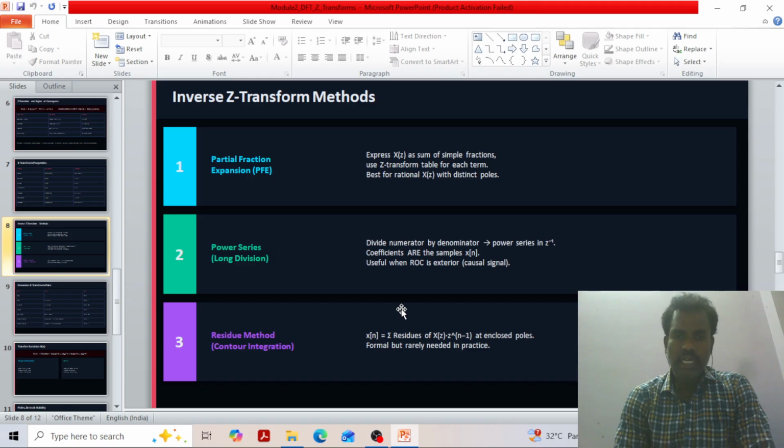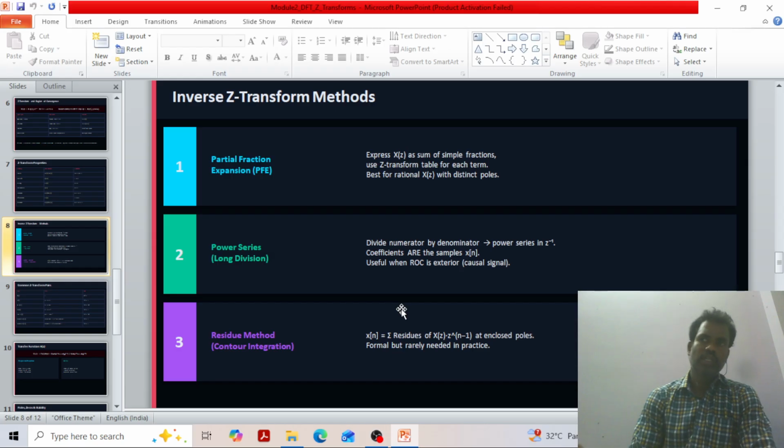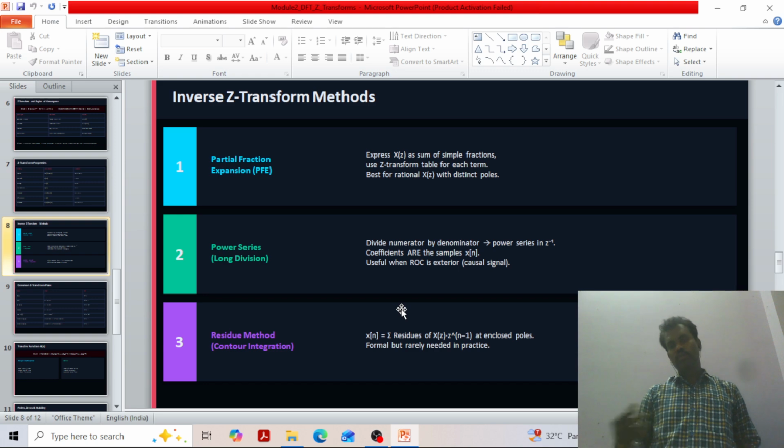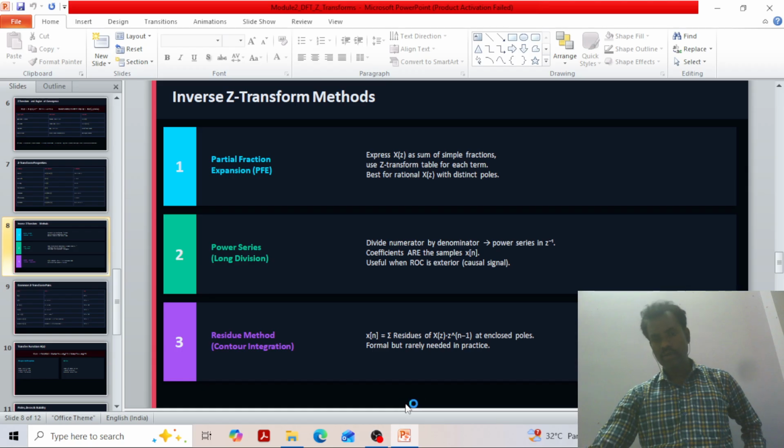The Fourier transform is calculated by using the FFT algorithm, the fast Fourier transform. There are many fast Fourier transforms based on radix 2, radix 4 and split radix. Many variations have been developed to improve the speed and to optimize the area, the power consumption and so on.